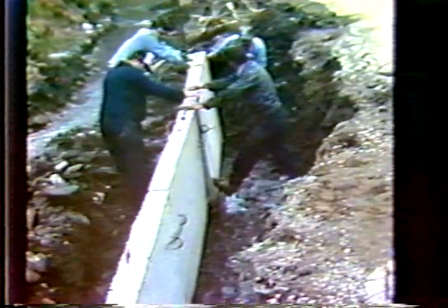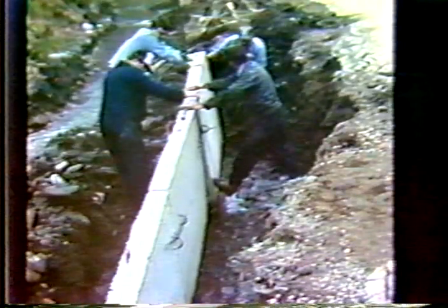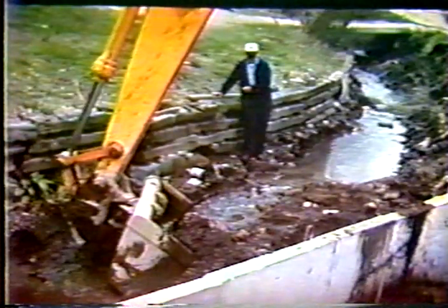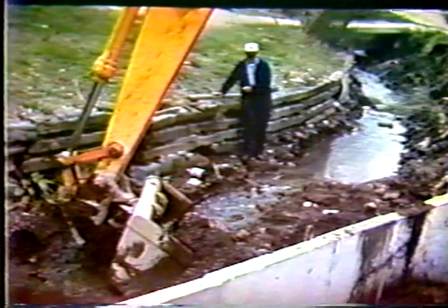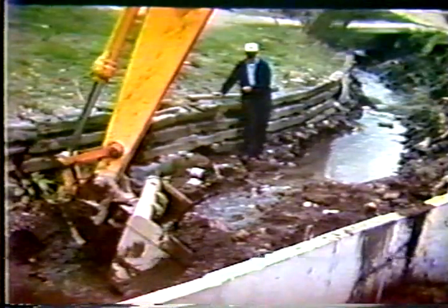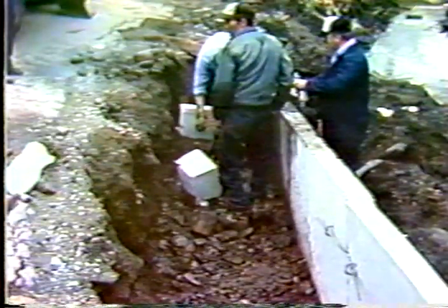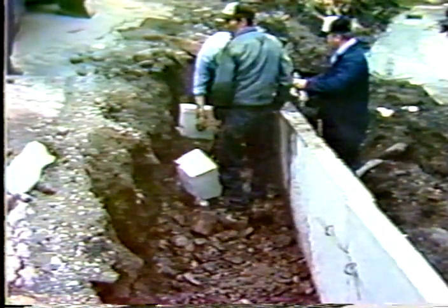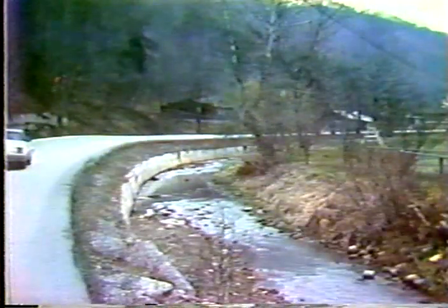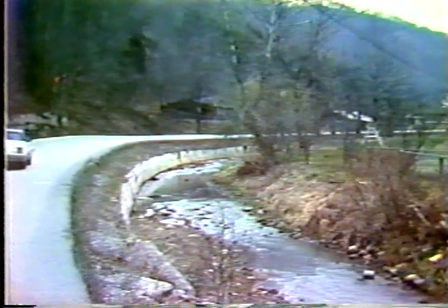Here's just another placement, showing placement of the sections using just equipment on hand. It's not very sophisticated backfill, but it works. He just scoops it out of the river and backfills. He backfills to about a third. Then he uses an anchor block, which is precast and stored at the concrete yard. He connects the anchor to the wall at about a third, and then he ties the steel coming out of the wall to the anchor block. Then he backfills on up using what's available there.